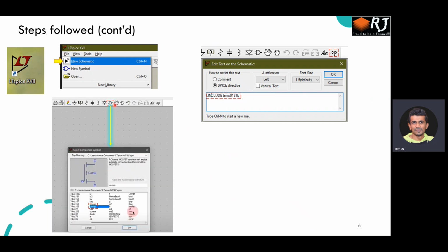That's how it works. And you can go to this particular symbol here, whatever you see as an AND symbol, right? You can click on that. There you will get all the options, including the user defined ones, or third party defined ones. Currently I have selected these two, that is CMOSN and CMOSP. That's why you see them here. The built-in options are also available, and you can refer to them later as per your need.